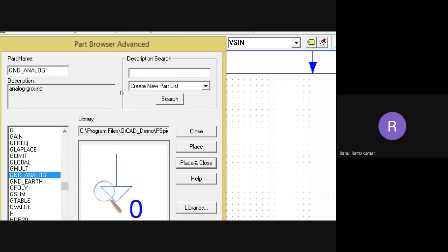This is required and very important, because using the ground, the simulator is able to understand which part of the circuit is my reference voltage, that is, which part of the circuit I should refer all other voltages to. You know what ground is? Ground is a reference potential to which the voltage of any other point is compared. When you look at the voltage at any point, it is the difference from the ground potential, which you should take as zero, though it may sometimes be taken as some negative potential. It depends, it's like a reference.